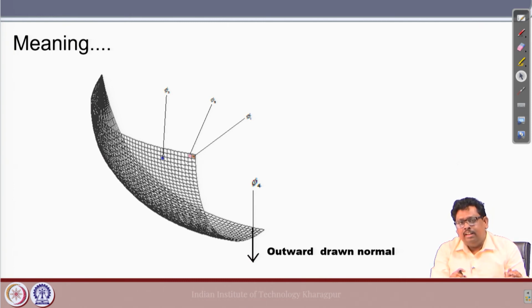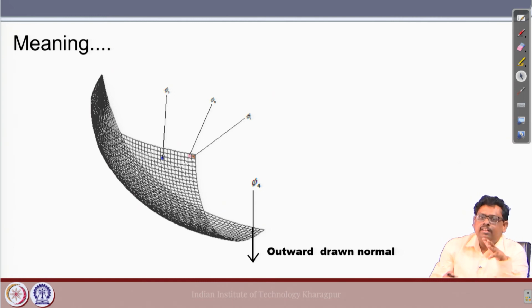If you remember, the finite element matrix is diagonally dominant, but here the matrix is dense, I mean it has values everywhere, right. It is not diagonally dominant. So, it is not essential that you take all the panels in sequential order or some order. That actually makes your life a little bit easier.